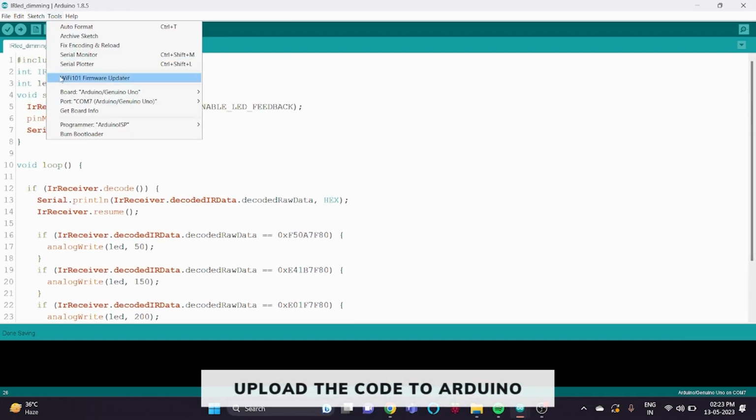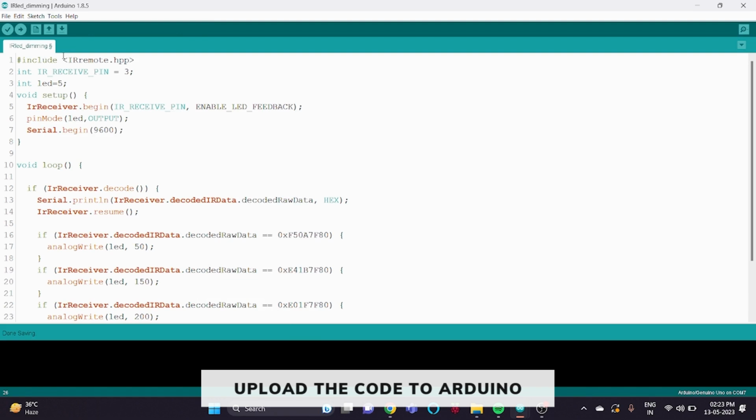Now click on tools, select the board as Arduino Uno and the port as COM7, and then click on upload. Your code will be uploaded to the Arduino.